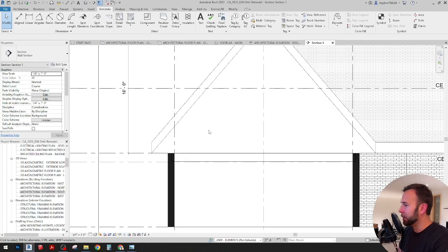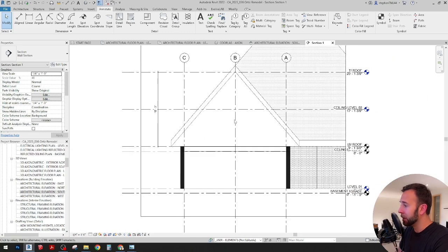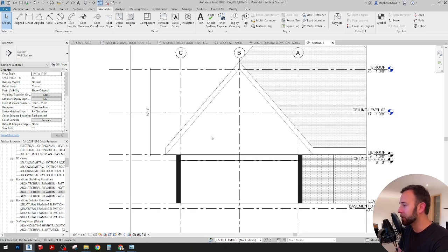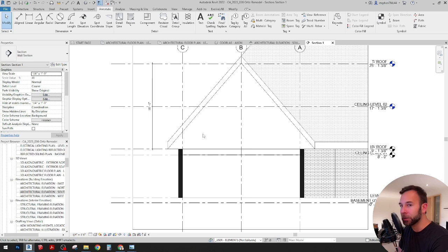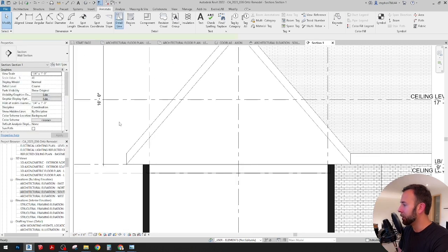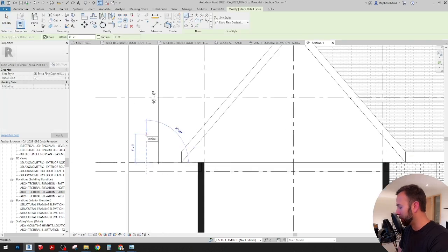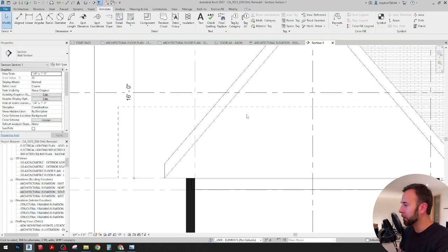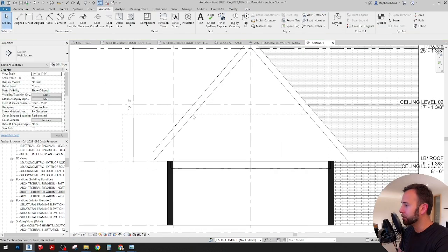And this is a good opportunity to see what we have in terms of head height clearances. Just a reminder, when you're doing plans like this for municipalities, and if they have FAR restrictions, floor area ratios, typically you want to look into what they have as allowances for head height, meaning square footage areas that don't count against you if they're under a certain head height. So I like to take my drafting line here. 6'8", 80 inches is typically your line that will strike for the head height allowance.